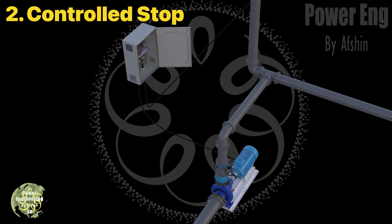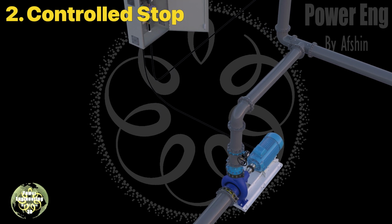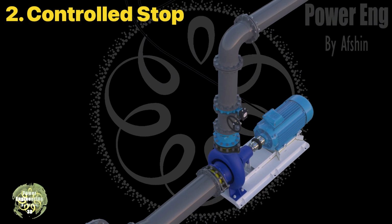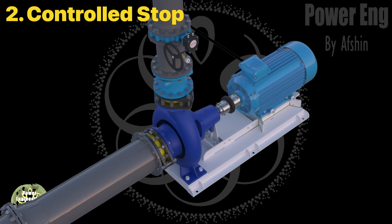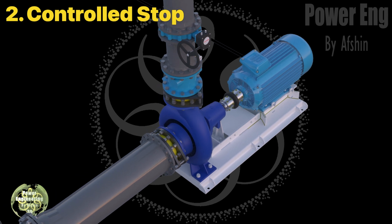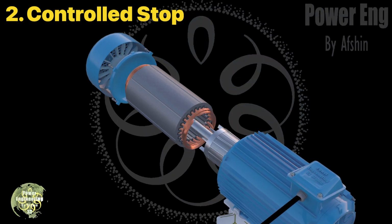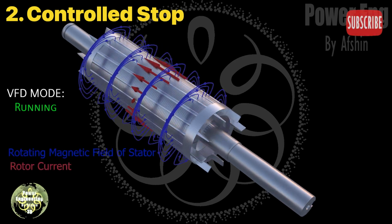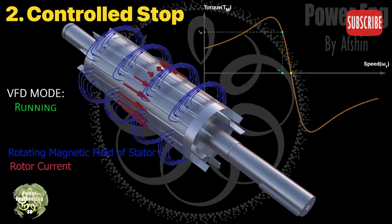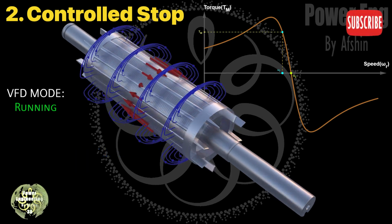Second method. Controlled stop. This method is suitable for light loads such as centrifugal pumps, fans, blowers, small packaging machines, and more. The stopping time can be set in the VFD's parameters, but it should be appropriate for the combined inertia of the motor and load. When the VFD receives the stop command, it gradually reduces the stator voltage and frequency over a specified time and slope to stop the motor.